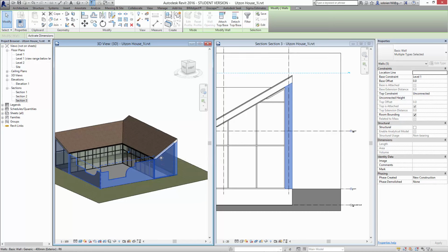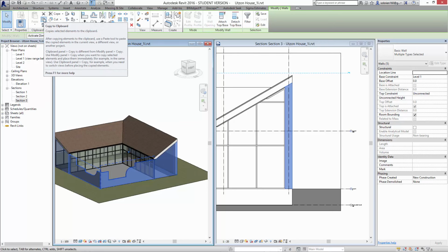walls in a loop. Because these walls already describe their position in plan view on the ground, we know that's where we want the foundation to be. We just want it to be a little bit lower. So the quick way of doing that is, now that we've selected the walls, we can copy them. So it's not the normal copy tool here, it's actually a copy to clipboard, which is these two little pieces of paper up here. So you copy to clipboard.